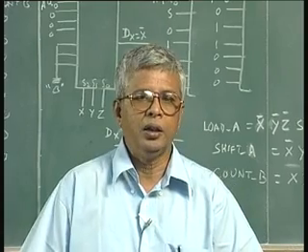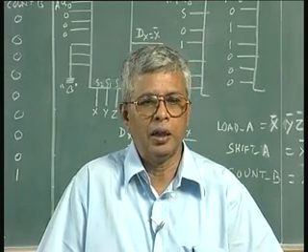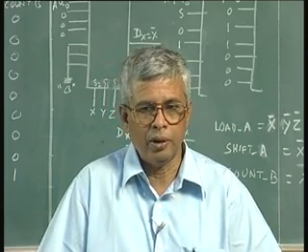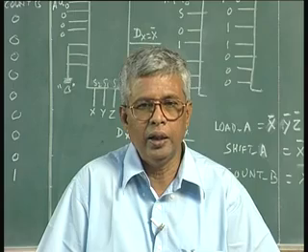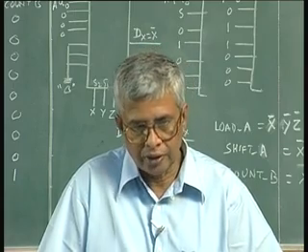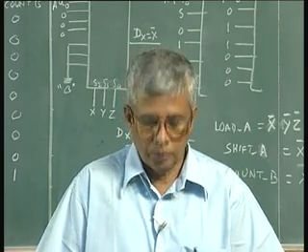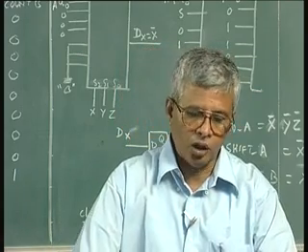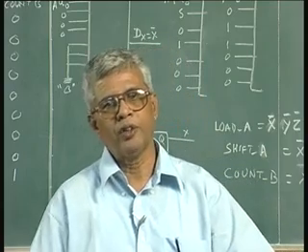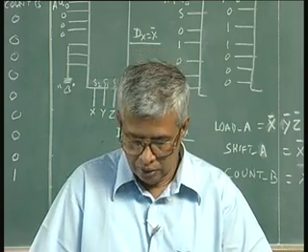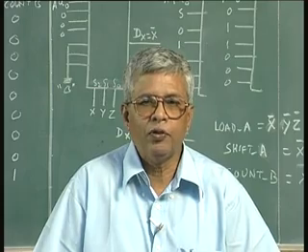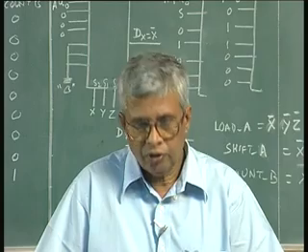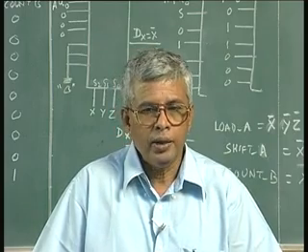Then we defined the sequential circuit, and the difference between sequential and combinational circuits. A sequential circuit is a circuit in which there is a storage element, memory, which is required in any real time system, any real life system. Then the basic building block of latches, leading to flip flops. We talked about different types of flip flops, and different types of triggering mechanisms, master slave and edge triggered. Using the flip flops as building blocks, we talked about counters, registers, shift registers, and simple sequential circuits.